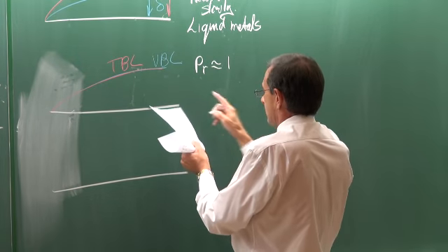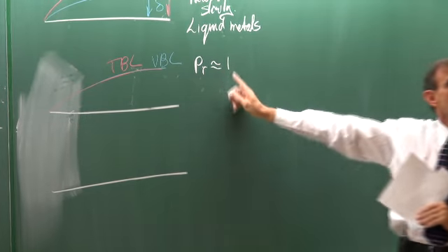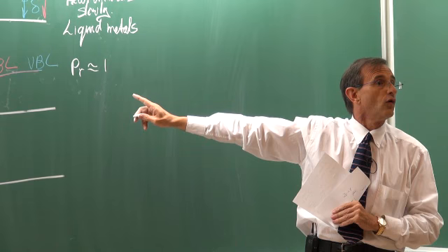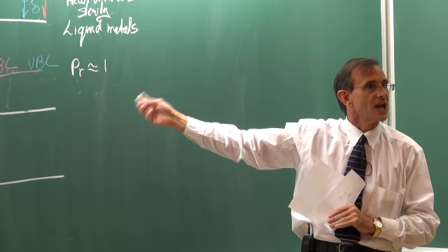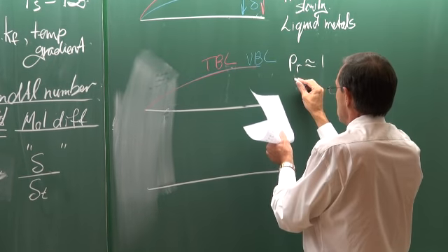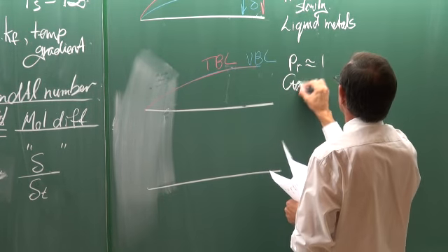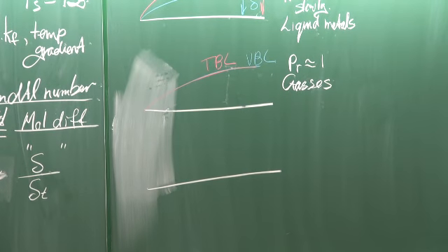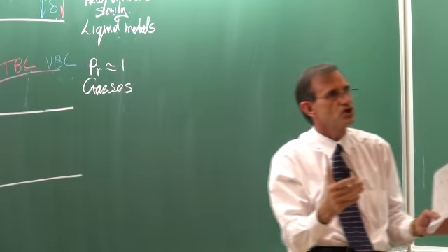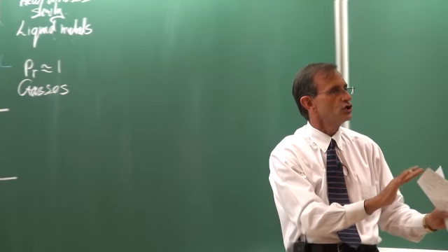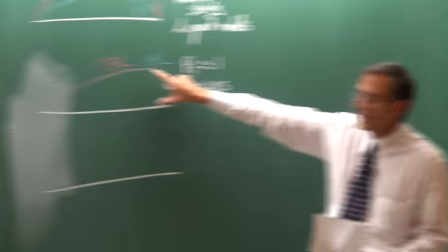This one is a very special category for us because many of the fluids that we work with fall into this category. For example, air and gases all have Prandtl numbers of approximately 1. Air is typically, depending on the temperature, 0.7 at about 20 degrees Celsius. So the order of magnitude is approximately 1. These two lines will not lie on top of each other, but close to each other.